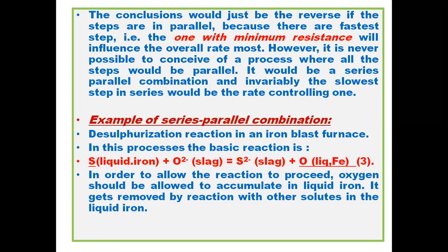It gets removed. Now see, if a large amount of oxygen gets accumulated in the liquid iron, what about the fate of the quality of the product? In the liquid iron, not only iron but some other elements are also there, and the temperature is quite high. In that case, the affinity of the elements other than iron is more towards oxygen. It gets removed by reaction with other solutes in the liquid iron.